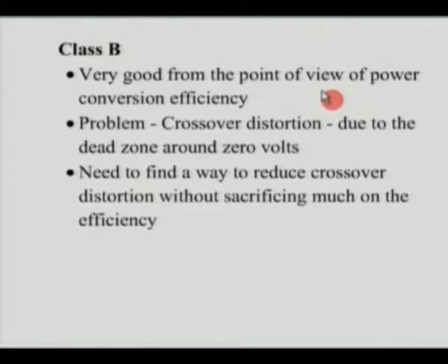This is because our ear is extremely sensitive. It can pick up even the smallest distortion, and again that is people dependent. Some people are much more sensitive than others, but crossover distortion is easily distinguishable. So if you give a signal, especially a voice signal, maybe a music signal, you put it through a class B amplifier and then you put it to a speaker, it will be very evident what is crossover distortion. The sound would be very displeasing.